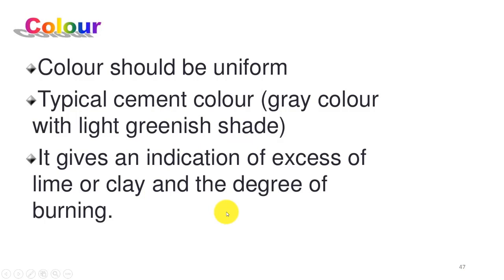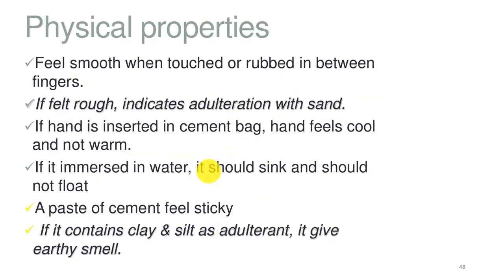When you have a cement consignment on site, what can you do to check the properties? These are basic properties that you can check on the site. First, you can touch the cement so that your cement should not be hot. If the cement is very hot, it means the hydration reaction has already kicked in. The formation of hydration products begins.